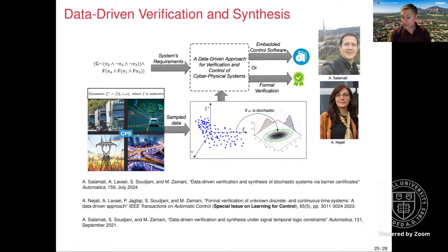So we extend to also control barrier, how to design a controller directly from data. From n input-output data, we can generate a controller without any identification. That's what we are promising here. No model identification. It's called a direct method. Go from data directly to analysis. Verify if it's safe or not. Go from data directly to the controller. Give me the controller based on data, no need for identification.